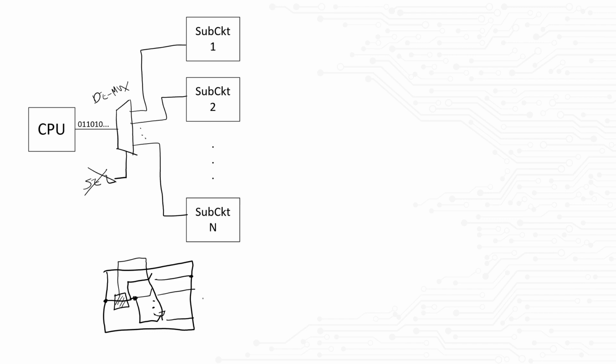If you didn't spell it out for the interviewer already, he might ask, what is this mux-like structure called? The answer, of course, is a sequence detector. The interviewer will follow up with, alright, so let's draw the state machine for detecting the sequence, like you mentioned, 1010.